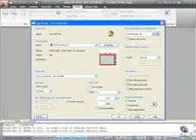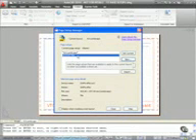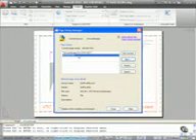I'm going to cancel the page setup, or am I? No, don't. You need to OK all those settings. So there's our A3 DWF plot. Now if I highlight that page setup there and then double click on it, it applies it to the current layout. So our A3 landscape layout now is using the A3 DWF plot style.